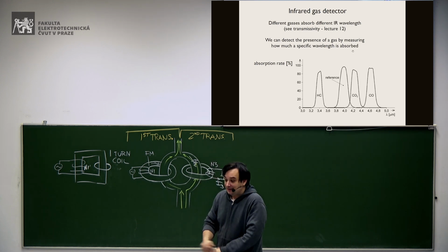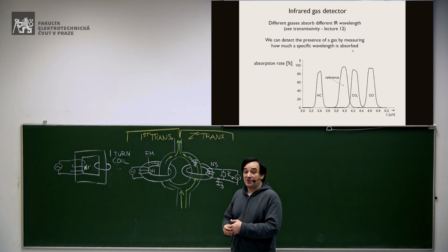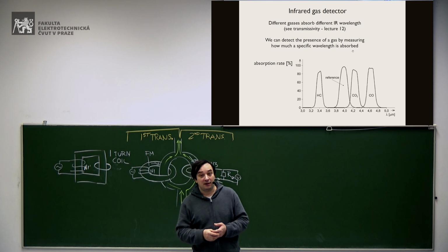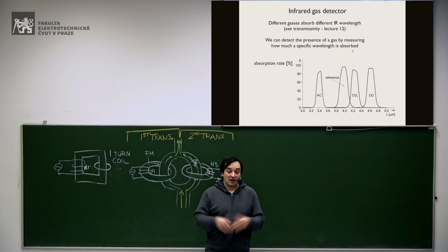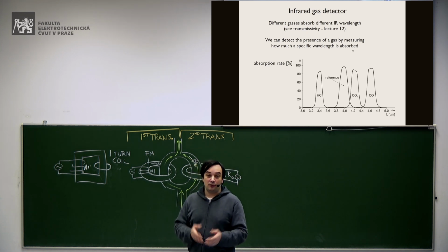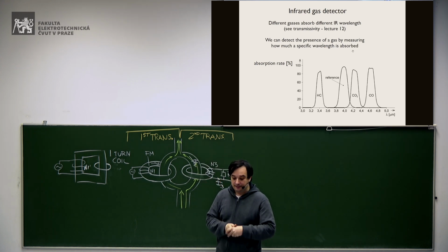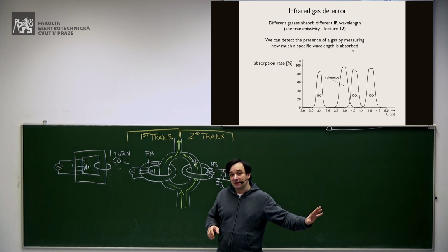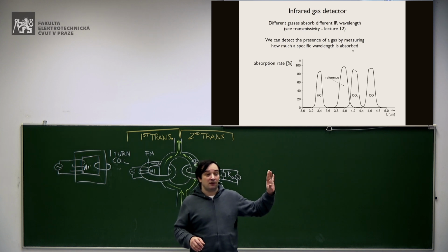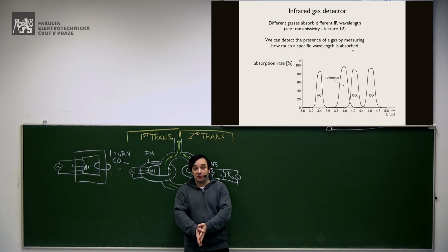In that case, I also specified that you can select a specific wavelength where you know that you have transmissivity of 100% in order to focus the filter of your narrowband pyrometer and measure the energy there. That was a problem for infrared contactless measurement of temperature, but in this case, it becomes a new opportunity.